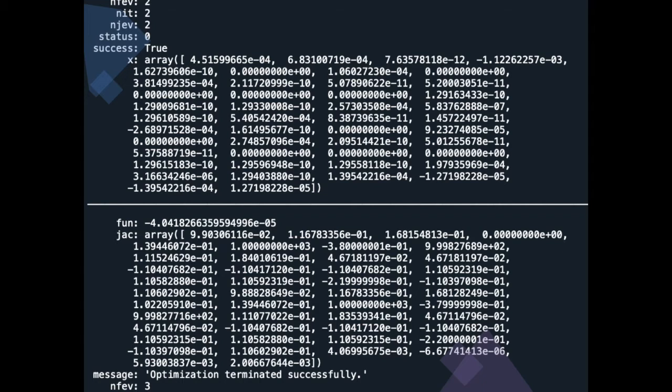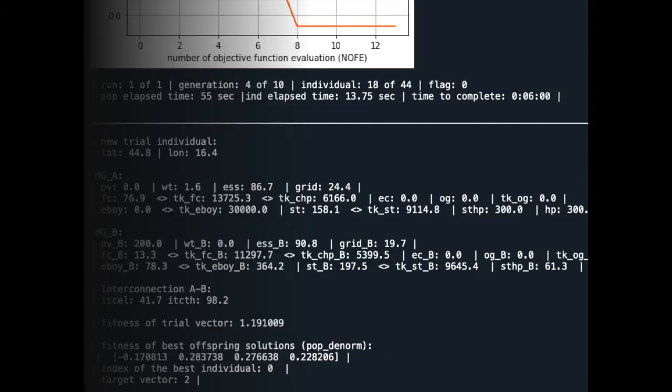The SLSQP minimizes a loss-profit objective function with constraints to balance electricity and thermal energy flows each time step. At the upper level, the evolutionary algorithm mimics genetic mutation of a population of individuals. Each individual represents a configuration trial. The chromosomes of the parents are the distributed energy objects forming the trial solution.